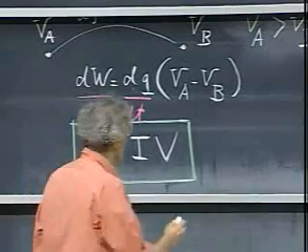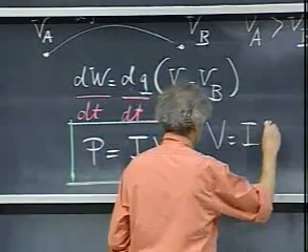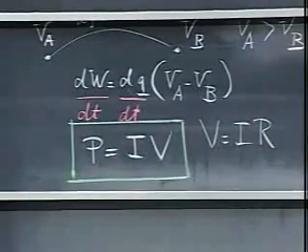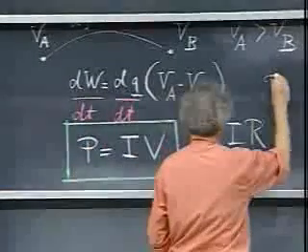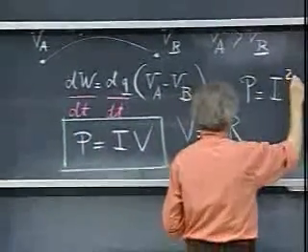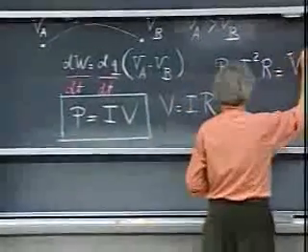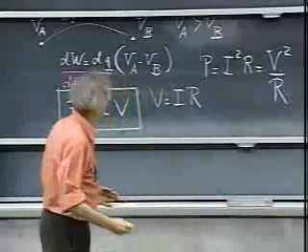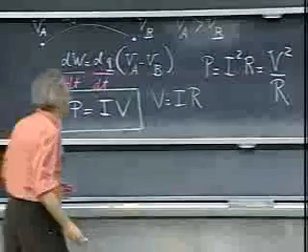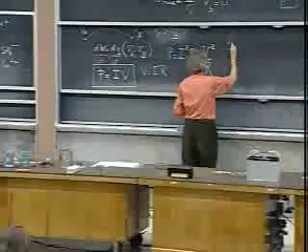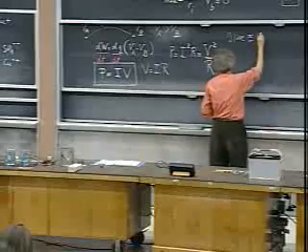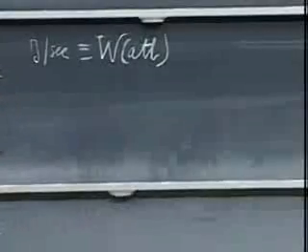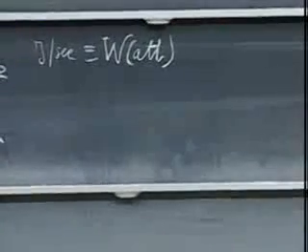If you also include Ohm's law, if you can use it, last time we discussed the limitations of Ohm's law, but if you can use it and V equals IR, then of course you can also write down for the power that it is I squared R, and it is also V squared divided by R. Power is joules per second, but we write for that watts, just a capital W, but it's named after the physicist Watt. So we always express the power in terms of watts.